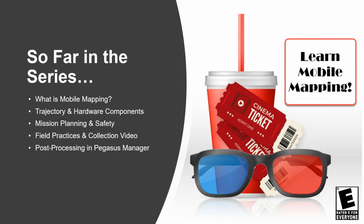Now, unadjusted data is great for asset inventory and GIS type applications. Projects where the accuracy requirements are not as stringent as, say, a roadway design project. But what if we have a roadway design project? How do we dial our results in further to meet high accuracy standards? The trajectory adjustment module in Pegasus Manager answers that question. And that's what we're going to be looking at today: the trajectory adjustment module, and more specifically, the multi-pass workflow.